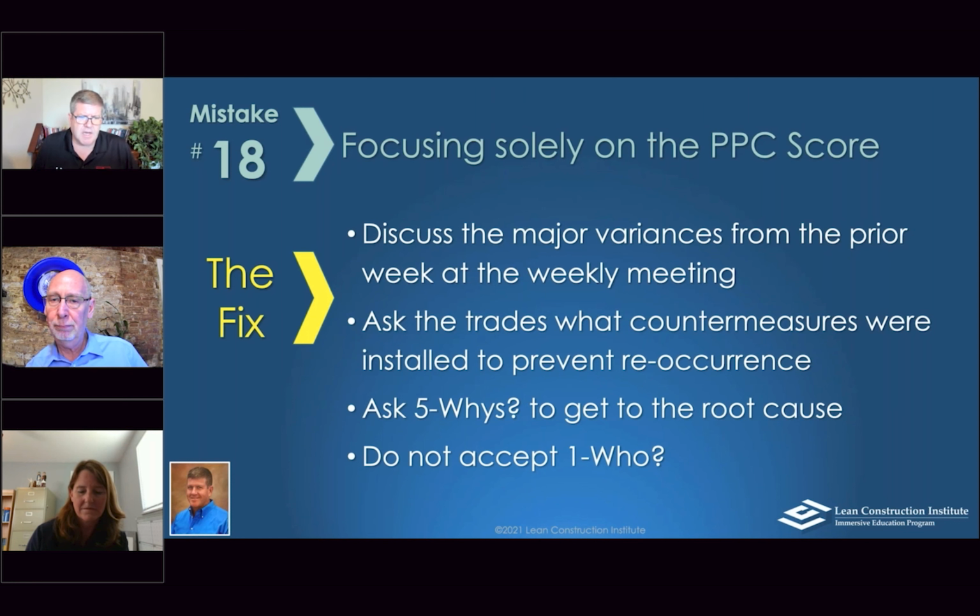Examples of phases. I know Julie and I both, and Sean both talked about different phases. So for design phases, for construction phases, a good way to identify your phase is by what Julie said was the length of work. It may be a demolition phase if you're in renovation. It could be a production phase if you're in the structure or the rough ends or the mechanical, electrical. So typical phases that we pull are typically like setup, like site clearing, site utilities, building the building pad, right? All the site prep and dirt stuff typically on buildings. Then you got structural, then you got concrete and steel, whether it's a steel frame, concrete frame.